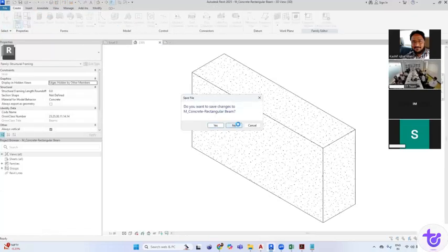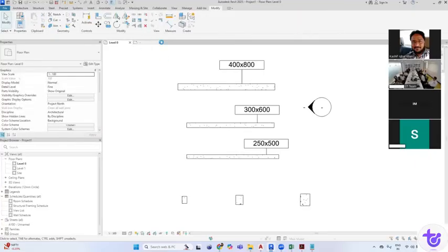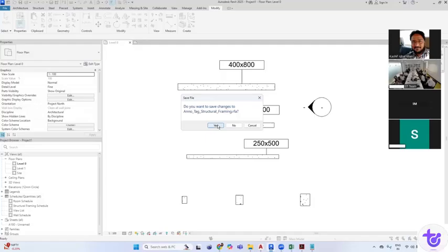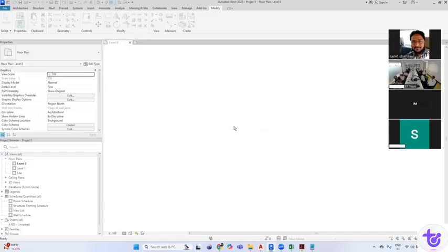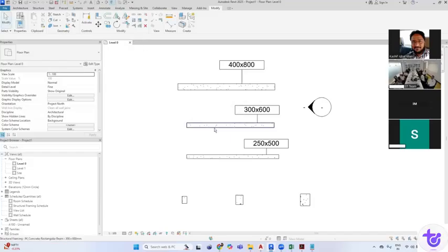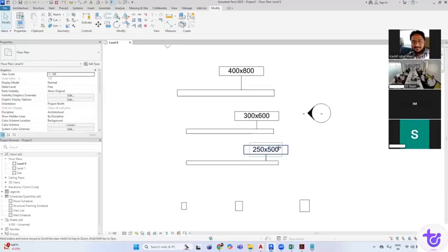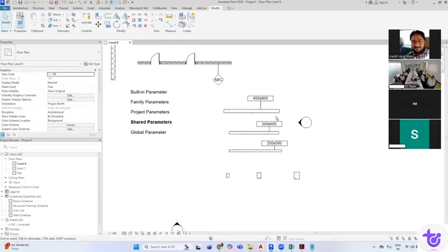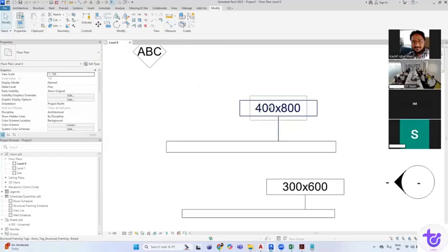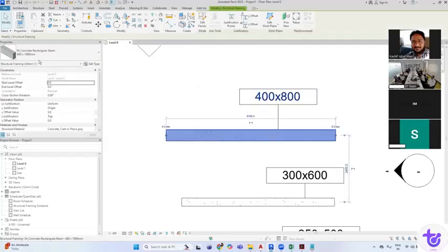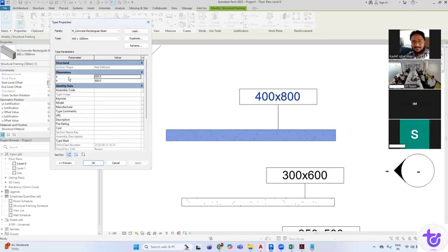Yes. It is applicable, because I just don't want to be specific to wall, to window, to anything, to steel beam, because we also have the other options, and for steel beams we have 2 or 3 sessions specifically dedicated. So I would prefer to take that for the steel beams in that particular session. But yes, it is applicable, and the process will remain the same. We have to check whether the parameters available there are actually family parameters or are they appearing in the schedule or not. This is the first thing we want to check. If you want to make them shared parameters, please go ahead.